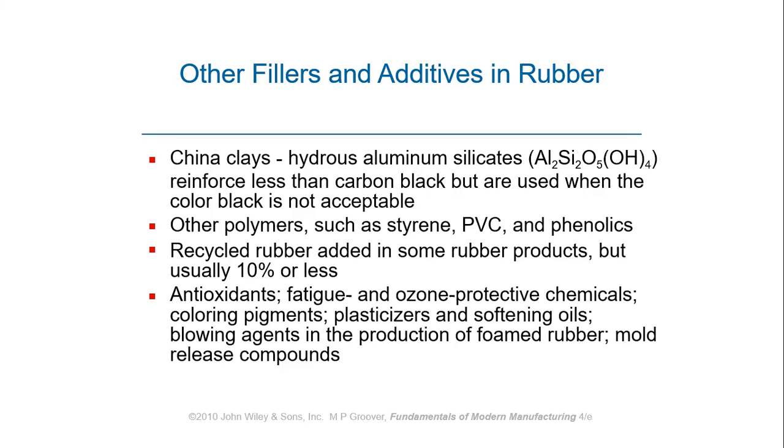And antioxidants. These antioxidants are also important to be used as additives in the rubber, because they provide fatigue and ozone protective chemicals. If you are using a rubber band and within 2 to 3 days the rubber property is degrading, then it will be very difficult. And that is why these antioxidants are required in rubber, to enhance its fatigue property and also provide ozone protection.